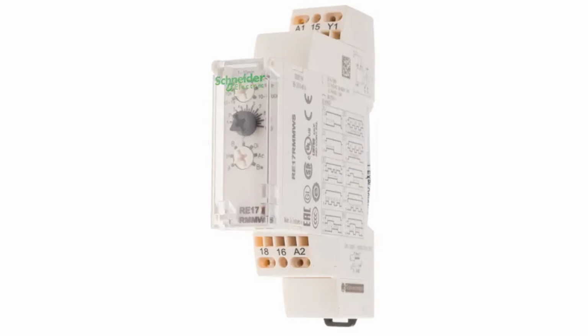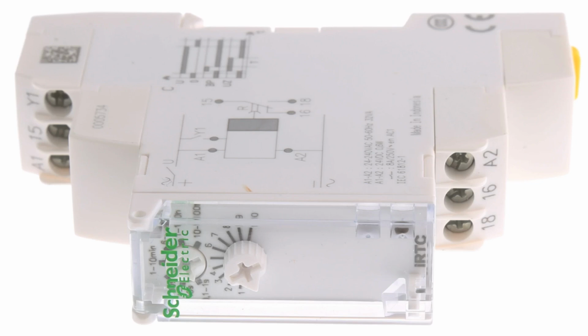The current rating specifies the maximum current that the time delay relay can carry continuously without overheating or causing damage. It's important to choose a relay with a current rating that matches the expected load current in the circuit. Operating the relay at currents higher than its rated value can cause excessive heating, contact welding, or damage to the